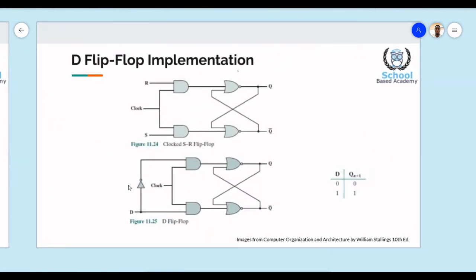So in a clocked SR flip-flop, a clock generally provides a stream of values 0, 1, 0, 1, 0, 1 going into our circuit. So if the value is currently 0, even though we get a 1 along any one of these inputs, we have to wait until the high pulse of 1 before that value is granted access to the general circuit. Inside of a D flip-flop